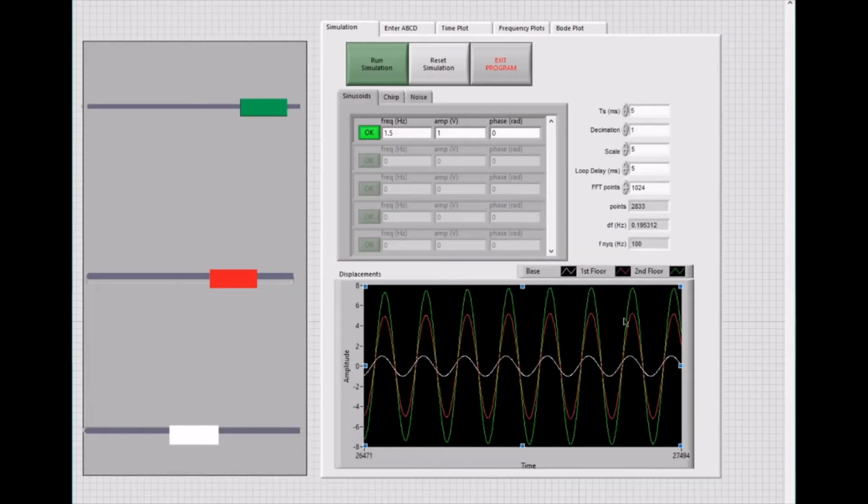So which one is going to be interesting? Let me think. The one frequency that's going to be really interesting is what's called the zero frequency, when omega is at the square root of k over m, which is the square root of 270, that's 16.4 radians per second, and you divide by 2 pi, you get a frequency of 2.6. So I'm going to put in 2.6.